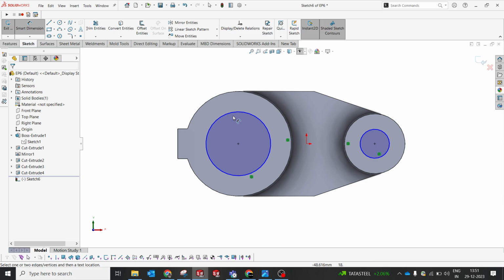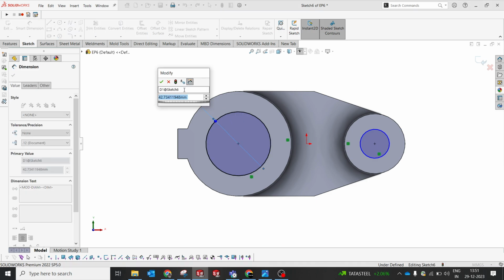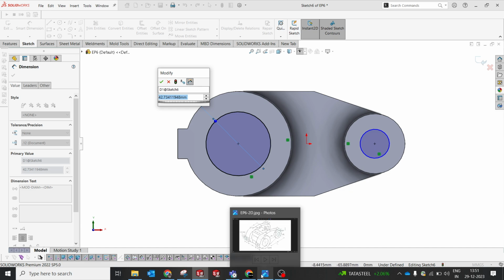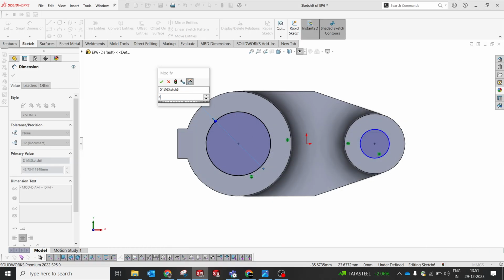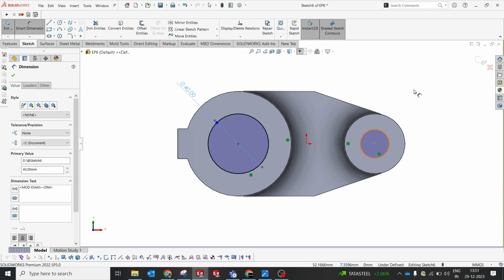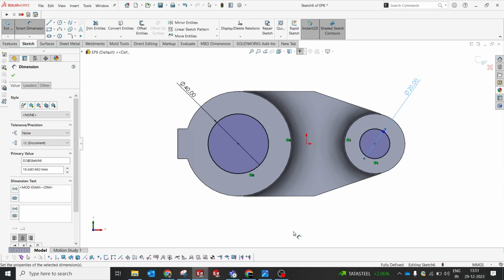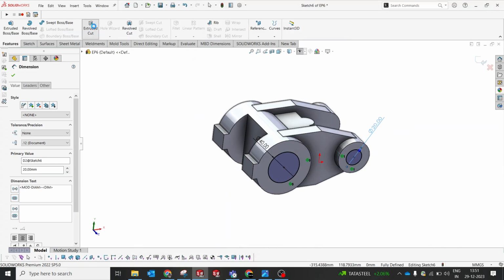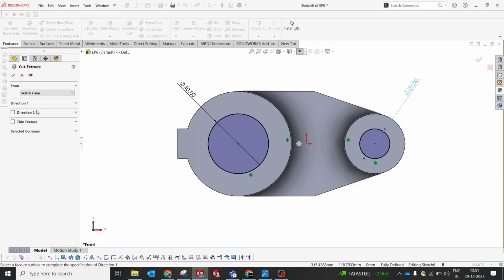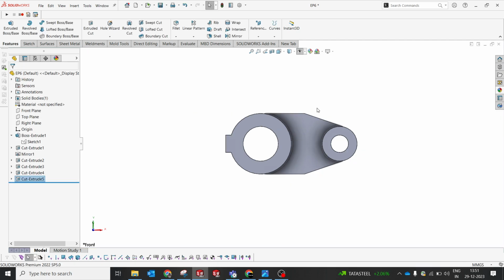So from a manufacturing point of view, I have done this, like even while extruding we could have done both circles as a hollow contour, but still thought of making it from a manufacturing point of view, so I have done this. So you can use another alternate option to make it as a single entity, I mean single feature. Extrude cut, I'm gonna select again both, yes, perfect.